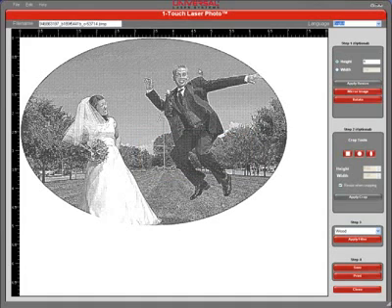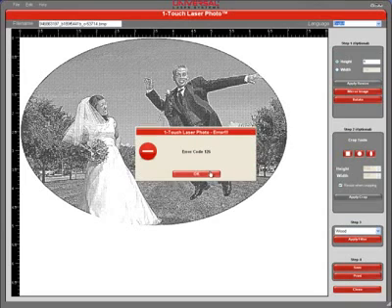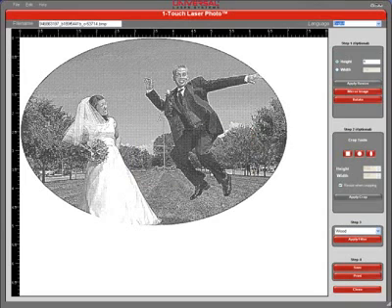You can also, if you use a current Universal Laser system, which is a VLS or Versa Laser Series, a PLS or Professional Laser Series, or an ILS or Industrial Laser Series, you can hit print directly. I can print from here, and I don't have the driver installed on here, but it'll open the printer driver automatically, linked to your system, and it will select the material that you actually have. So it will be already pre-selected to the wood. All you have to do is select what kind of wood, and then how thick, and then let it continue on.